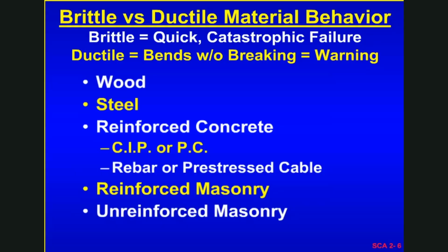Precast elements built in a factory can be very, very strong, but the joints in them will determine how ductile the building is. If the joints are done very, very well with good steel embedment and so forth, that can make a fairly ductile building. But if they're not, as is the case in a lot of the U.S. away from earthquake zones, those structures may be quite brittle.